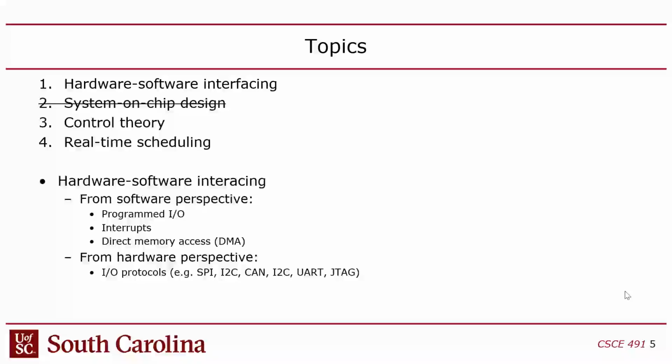Now, obviously, we can't design physical circuits that talk to other circuits across the wire because we don't have control over the hardware anymore. But one thing we can do is use something called bit banging, if you've ever heard of that, which is where you write software to implement these protocols directly, like you drive the protocols from software. Now, no one ever does that. In reality, these protocols are driven by specialized circuits.